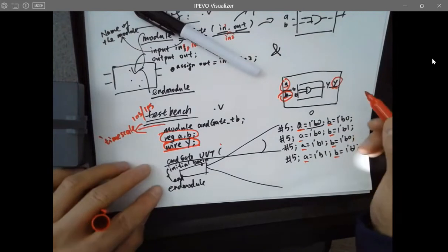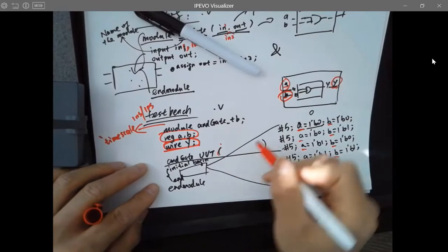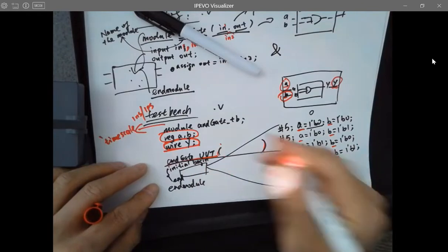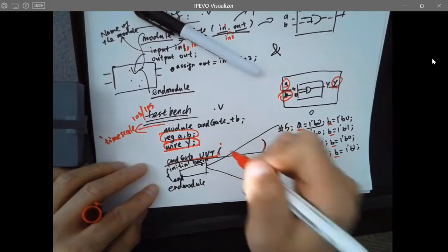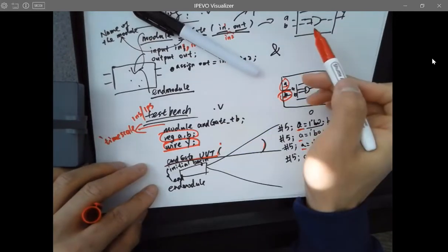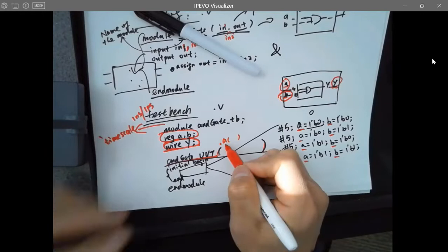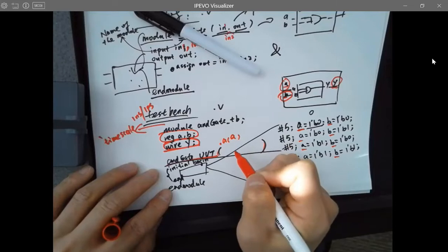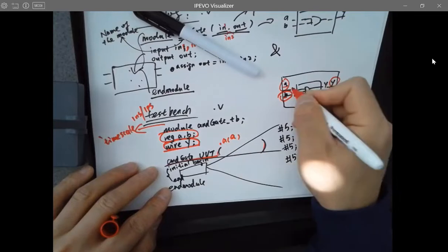Okay, then how to make the connections between the test bench and the device itself, in the parentheses in the test bench right after you instantiate it? It's going to be dot, and the signal line right behind the dot, keep in mind, is the signal from the UUT. Dot A, parentheses: A is a signal line from the UUT, and it is being connected to A from where? The test bench, which is this signal. I'm making the connections.